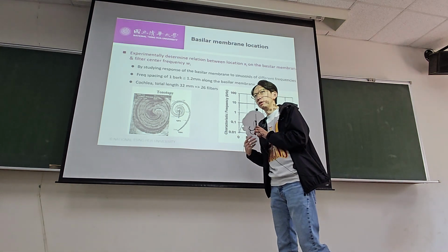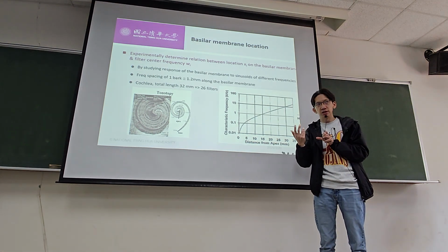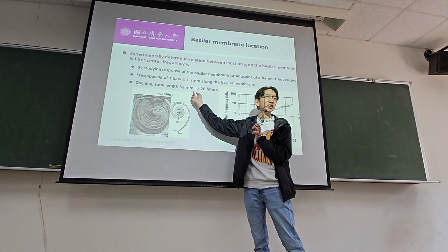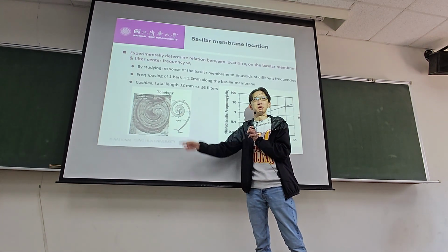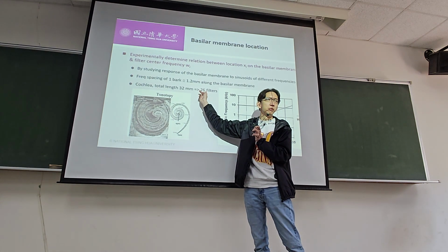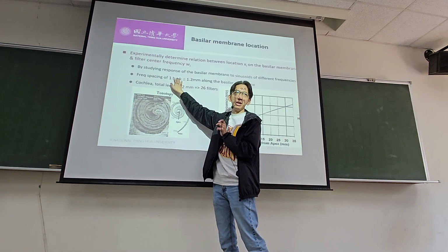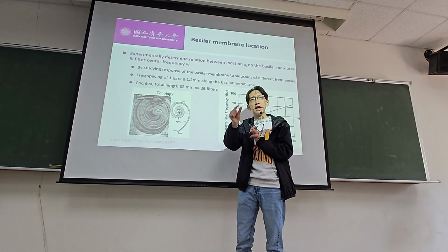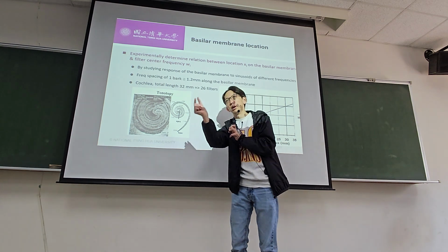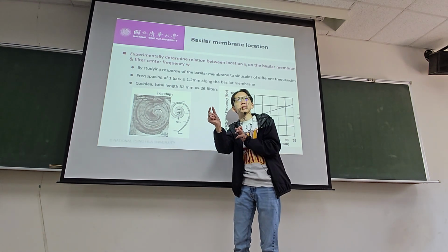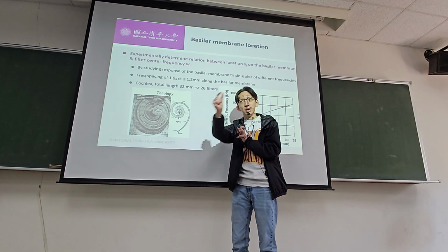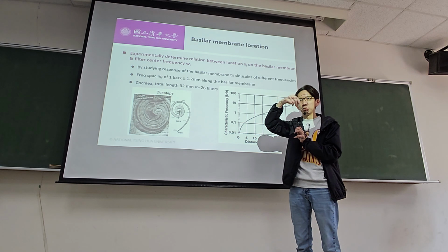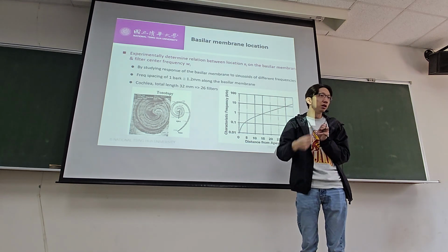If you ever do MFCC computation with a mel filter, you say you design 26 mel filters, the idea is because of this. Mel filter, then you do cepstral coefficients. And the idea is because the cochlear membrane is of this particular length. You will find that one particular Bark is about 1.2 millimeters along the basilar membrane. That means about every 1.2 millimeters, it has a new bandpass response. So we can then separate these physical properties of our basilar membrane into a set of discrete bandpass filters. Can you imagine that?